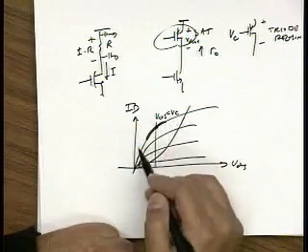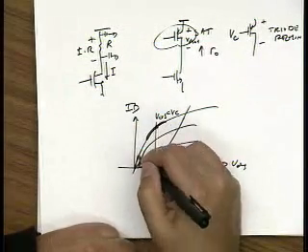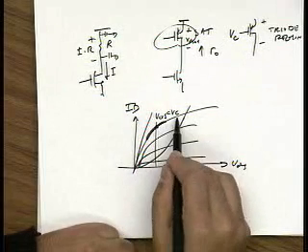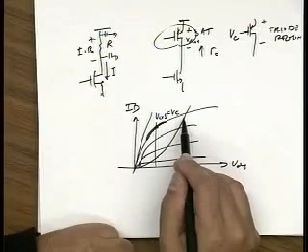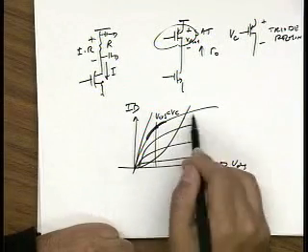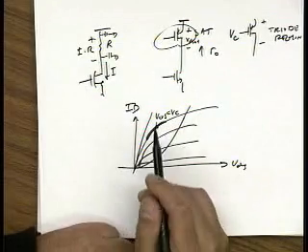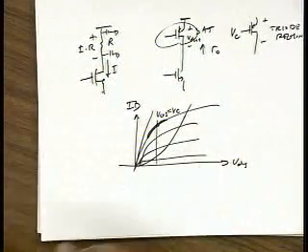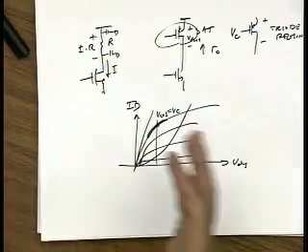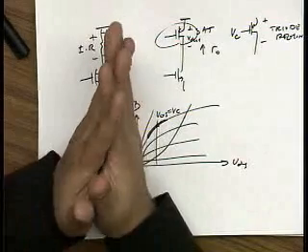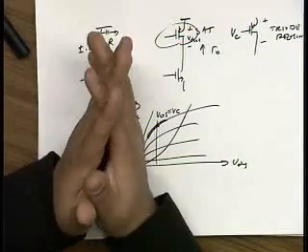And you can see that it has some curvature to it, so it's not a very good resistor. In fact, if you use it over here, it's the most linear region, and the higher you put the voltage across it, the more nonlinear it looks, right? So there are some restrictions on the voltage swing you can put across it and its linearity, but it's actually a pretty decent resistor. It's not a very precise resistor, though. So it has the same problems as the other resistors. In fact, the variation might be even more. And it's also quite a nonlinear resistor.